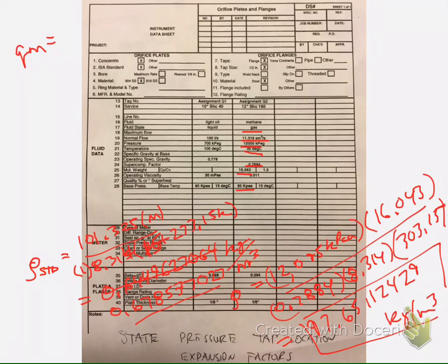So I'm going to go to the Orifice Sizing program in my calculator, and it's asking me right away for my maximum flow. And of course, here once again, this is a normal flow. So when we enter in our flow rate, it's going to need to be the maximum flow rate, right? So to figure this out, we need to multiply that flow rate by our density here. I'm going to go ahead and do that. I've got to exit my program. I jumped into it a little early again.